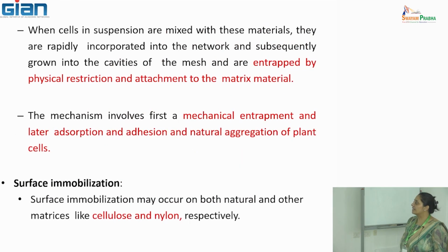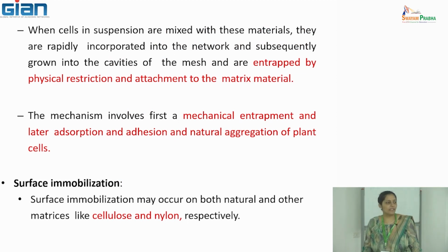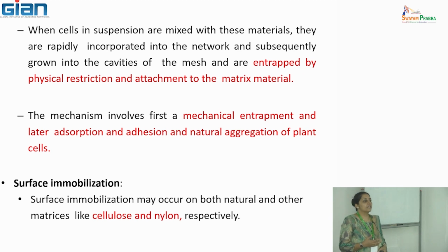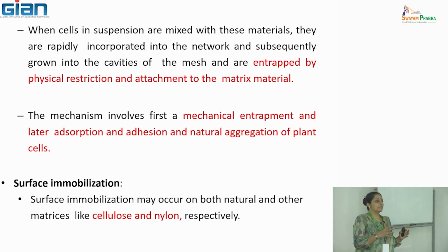Now, coming to the reactors which can be used for immobilized cells, how they are different from stirred tank reactors. They are generally packed columns. So these packed cell reactors have a limitation of large pressure drop, because how to improve the mass transfer requirements in these? The improvement in mass transfer requirements is done by converting these packed bed columns to fluidized bed columns.